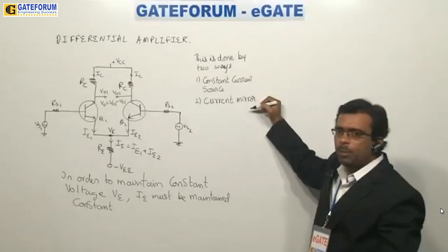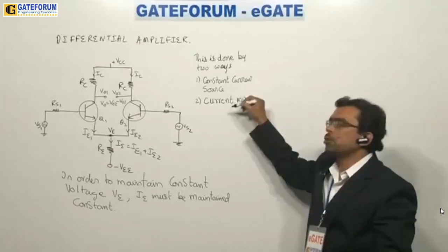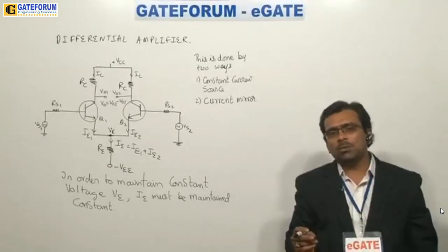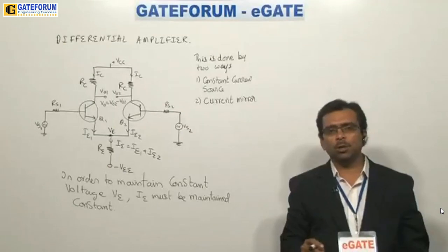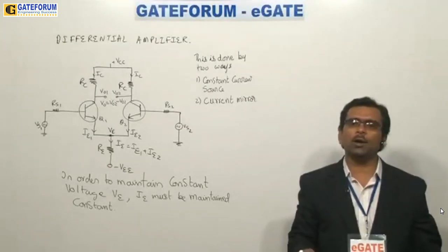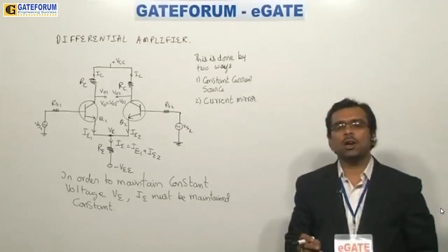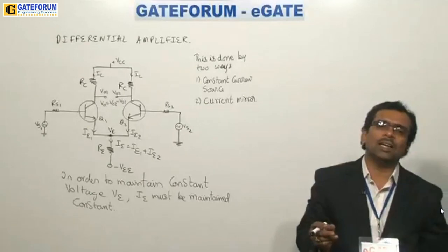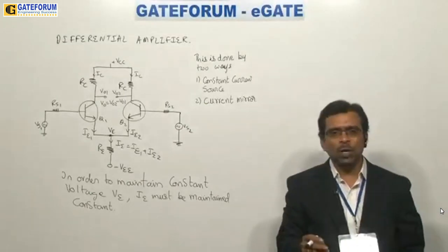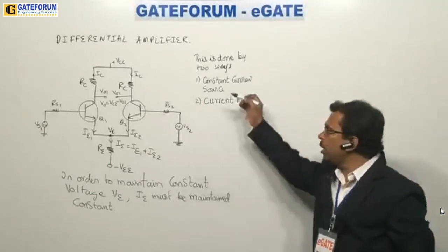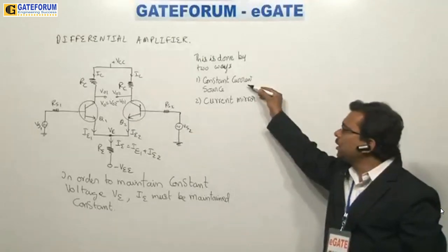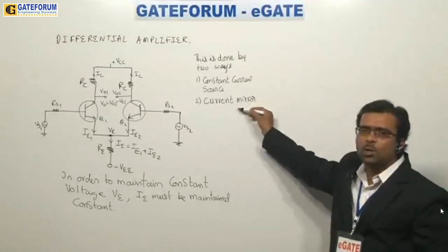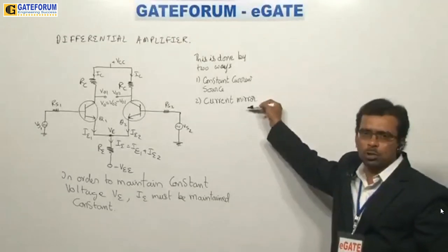When you observe these two carefully, this constant current source was initially the first circuit which was used, but this circuit has a problem. The Zener diodes, ordinary diodes and the transistor used have a dependency of current value on temperature. When temperature changes, the performance of this diode and transistor currents also changes. Due to that reason, this circuit will not be able to produce a constant current value, and it has become a flop model. So instead of using this, we try to use the current mirror. We call these two active loads.